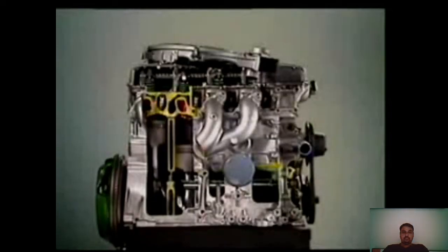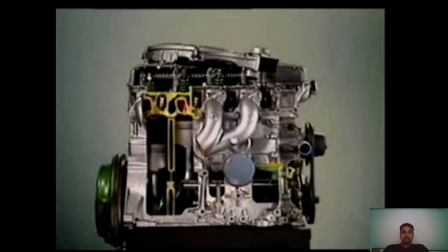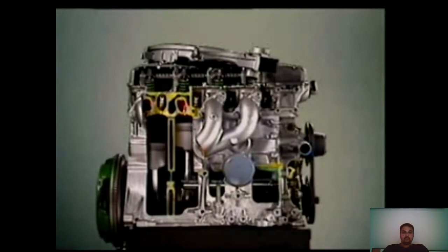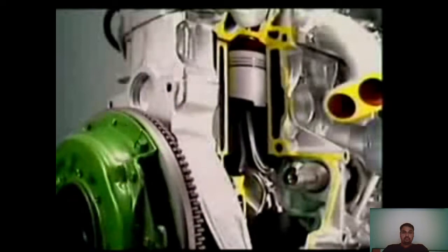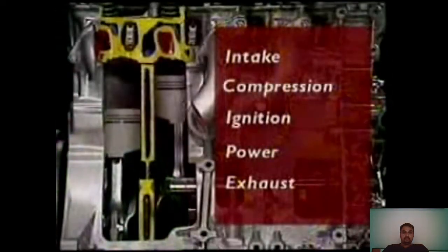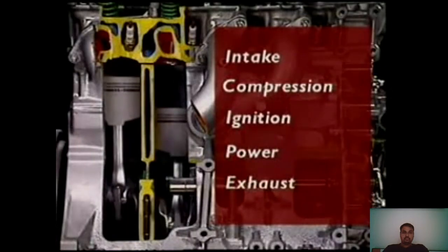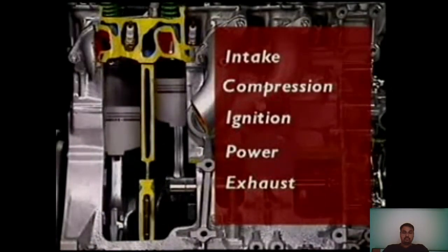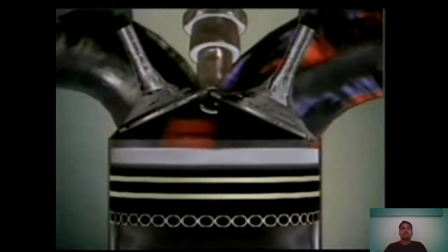What is a stroke? It's the movement of the piston from top dead center to bottom dead center. Calling an engine 4-stroke means its engine cycle has 4 strokes. A 4-stroke petrol engine uses internal combustion, so those 4 strokes must include the 5 key events common to all internal combustion engines: intake, compression, ignition, power and exhaust. Let's look at a simplified model.